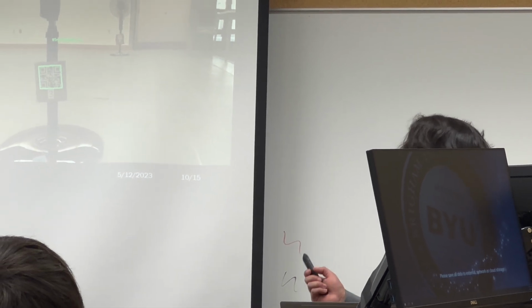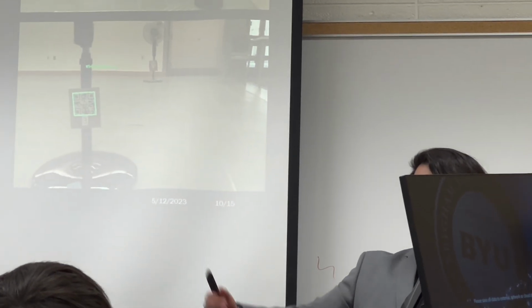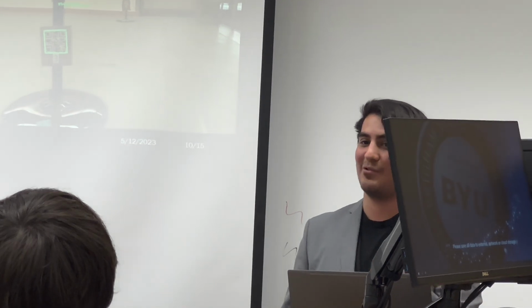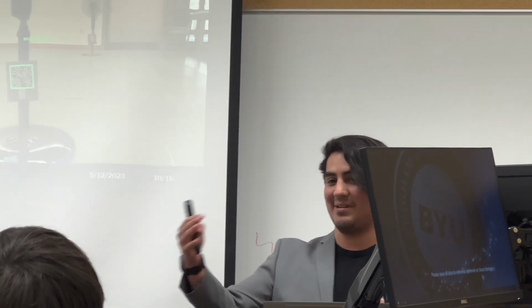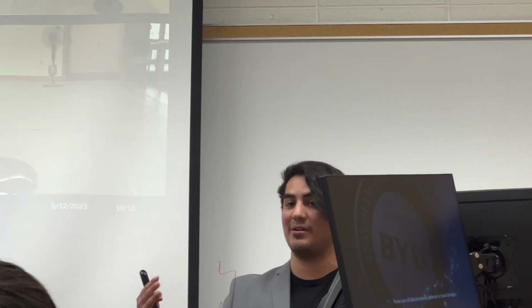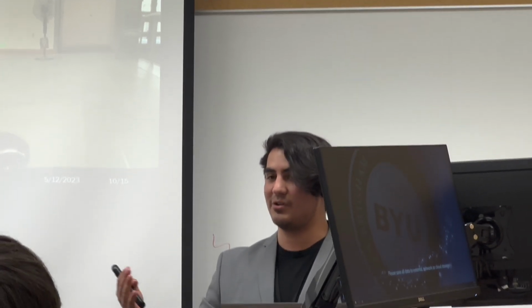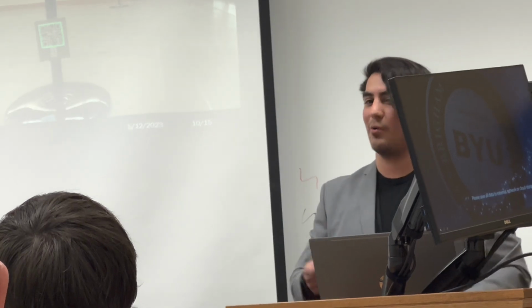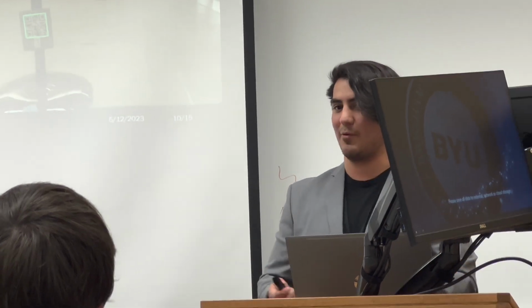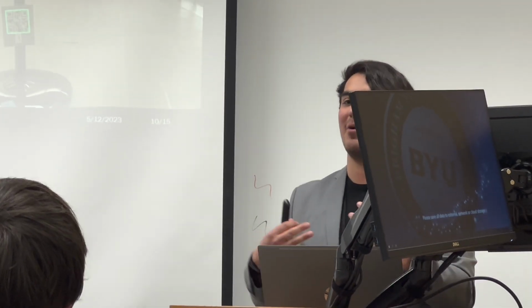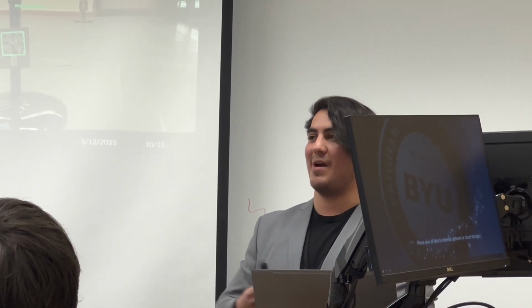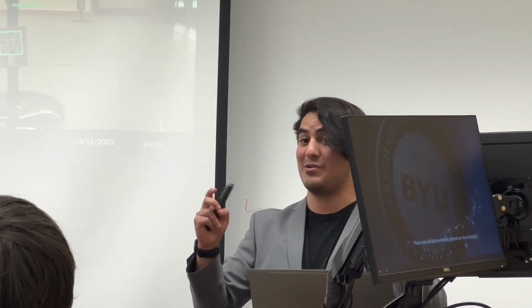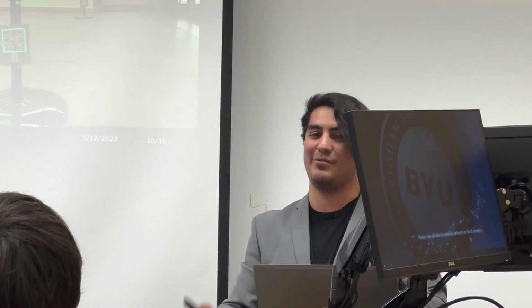If the camera quality was better, we could probably detect it far away. With a large commercial drone, with really good resolution, we could detect things far away. That probably wouldn't work for this experiment, but with a better camera, we would see things farther. But with our Haar cascade that we trained, we found there was a distance at which, even though you could tell as a person, oh, there's a fan right there, the drone wouldn't be able to detect it.